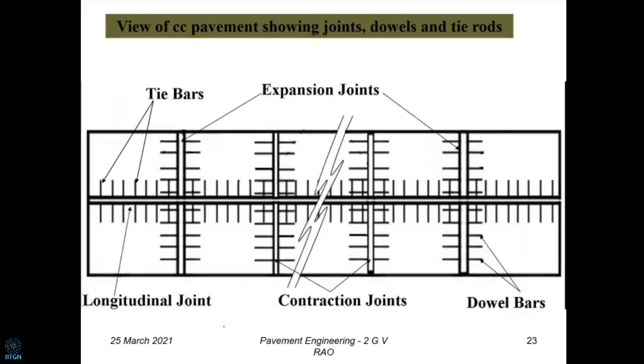So that was what we call plain concrete pavement, jointed plain concrete pavement, and again it gives you one more expectation. One is that even though the blocks have load transfer devices, naturally in summer they may expand. So if the blocks are just next to each other, naturally they are going to get crushed. So there will always be an expansion joint between the blocks. In the same way, it can contract also. So apart from these general joints, which are for dowel bar and tie bar, we also have expansion and contraction joints, and a third kind of joint is obviously the construction joint.